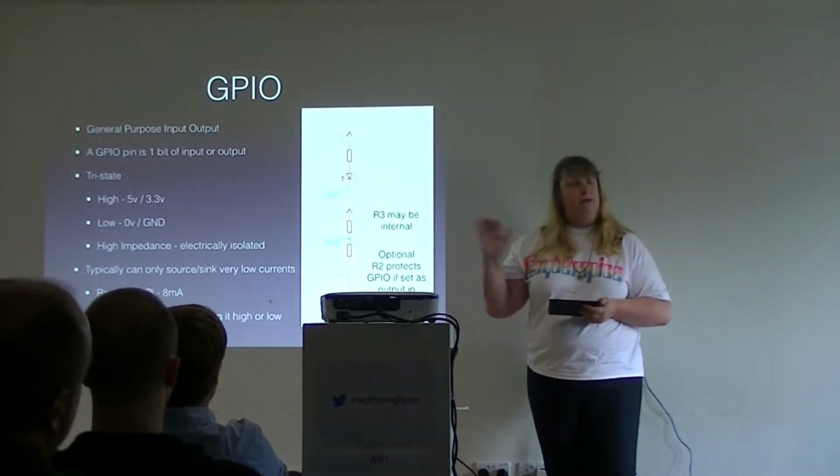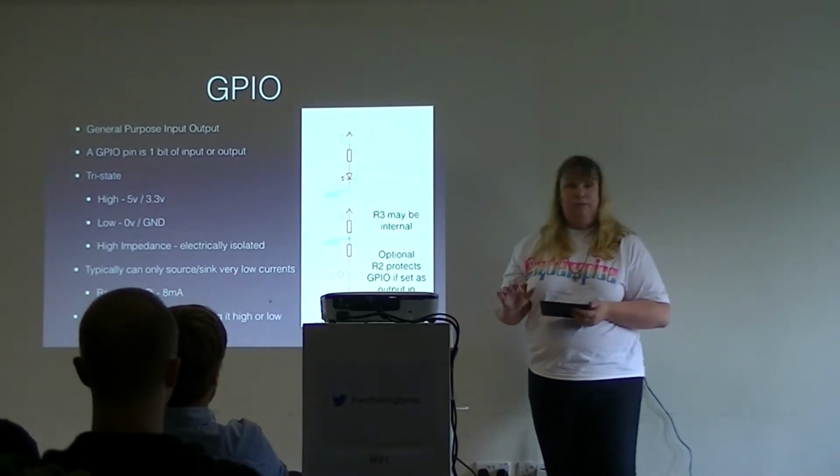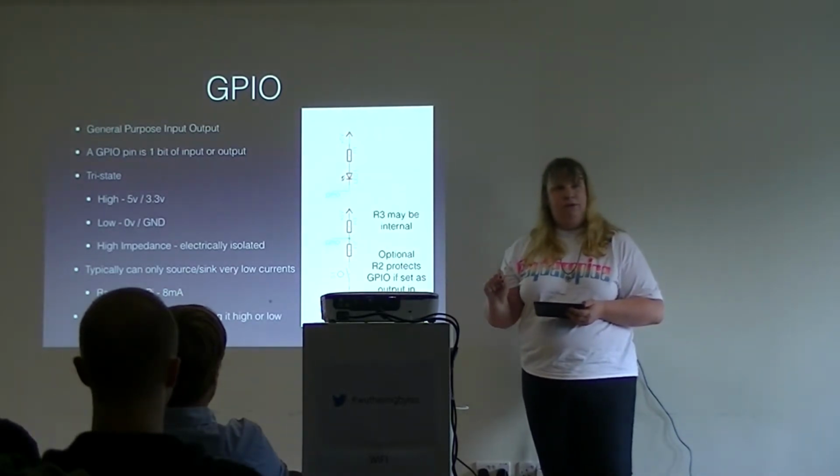So what I actually do, I don't use the pins directly, I use an I/O expander on my Pi, so that all I do is blow up a 2-quid chip rather than the Pi.